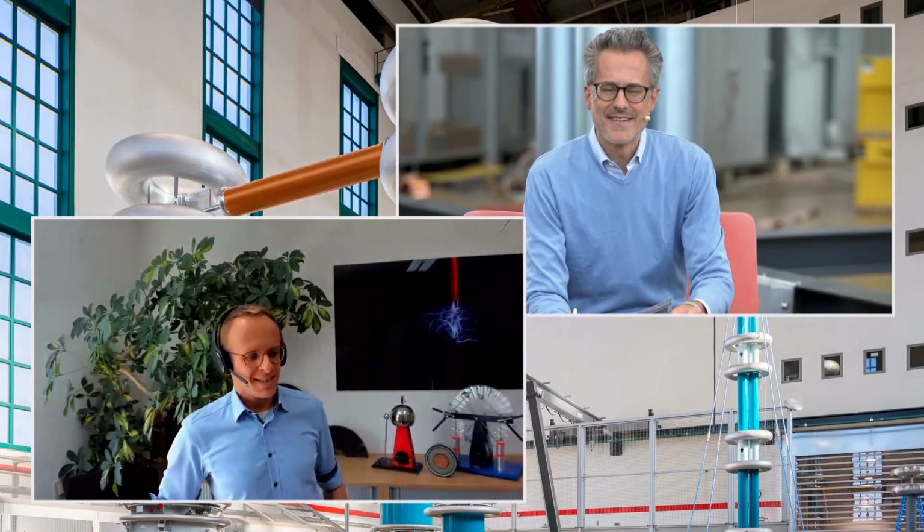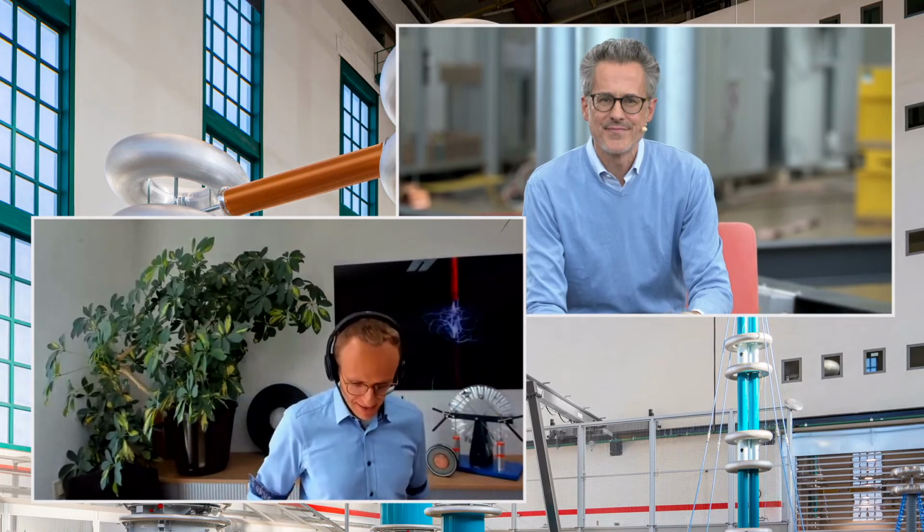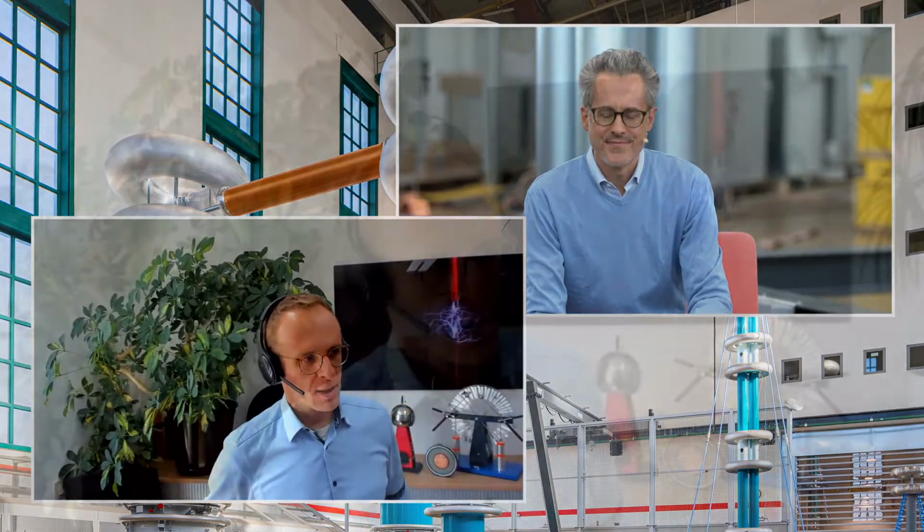So also in my eyes, the cable joints, of course, are quite loaded components because it is an insulation system consisting of different materials, with different thermal electric behavior. And again, there's still a lack of understanding or deeper insight into the behavior of these materials or material combinations at DC voltage.